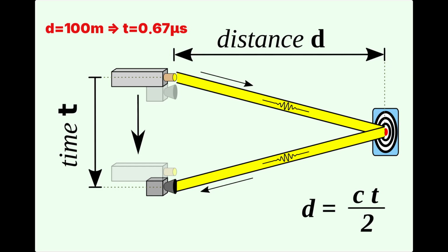All the problems and challenges regarding LiDAR come from the fact that we have to make sure that we know what distance we have measured. If we are trying to get the speed, we have to measure at least 2 distances at some time interval, and make sure that those 2 distances are from the same object. If we measure one distance from a car and another from some road sign or a motorcycle, that's not going to be the speed of the car.